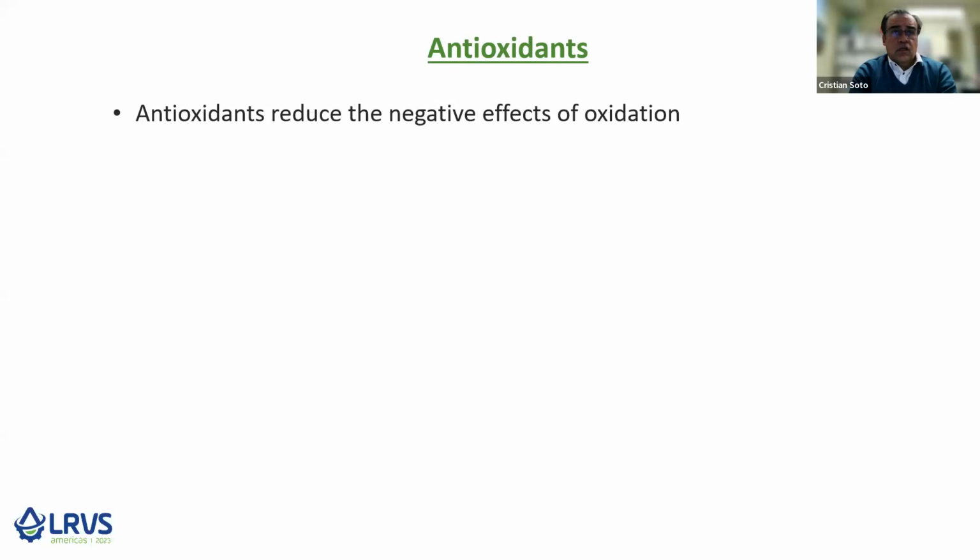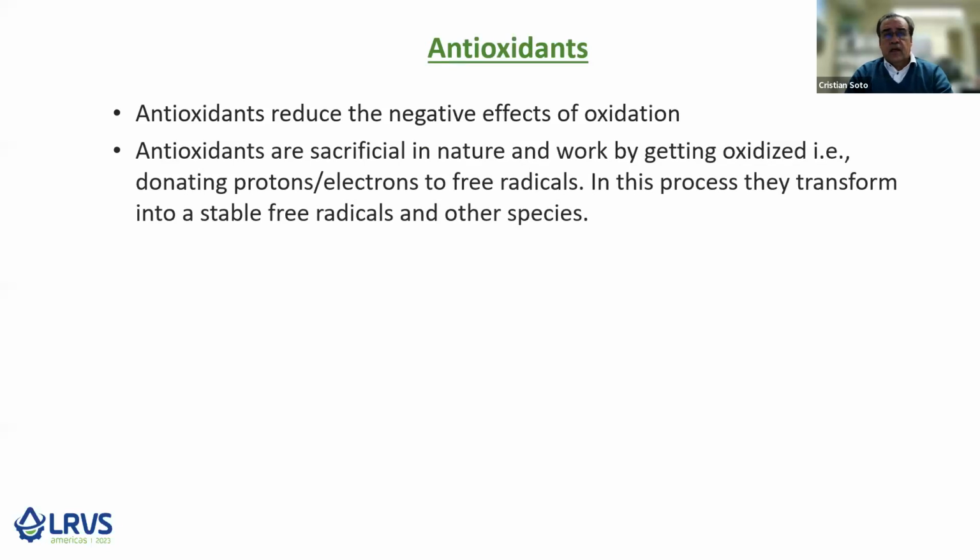Antioxidants. Since oxidation is a bad actor, a bad process for the life of the lubricants, lubricants are formulated with antioxidants, and clearly they are added to the formulations to reduce the negative effects of oxidation. Antioxidants are sacrificial in nature and basically work by getting preferentially oxidized over the oil that they're intending to protect. In this process, they don't just, of course, disappear.